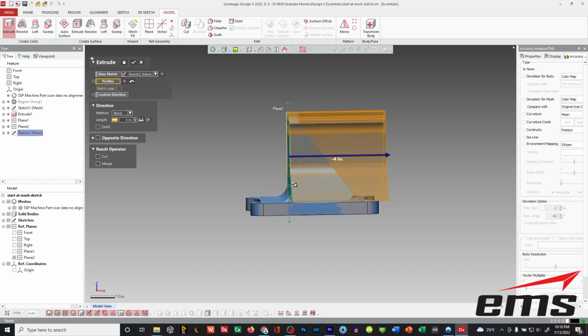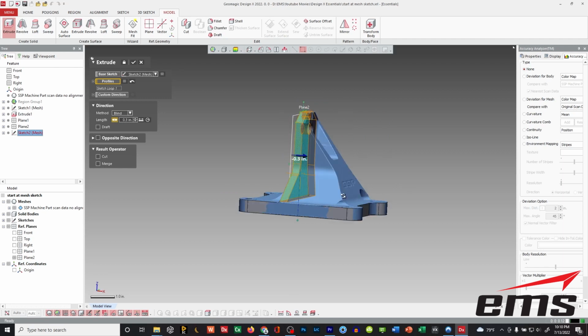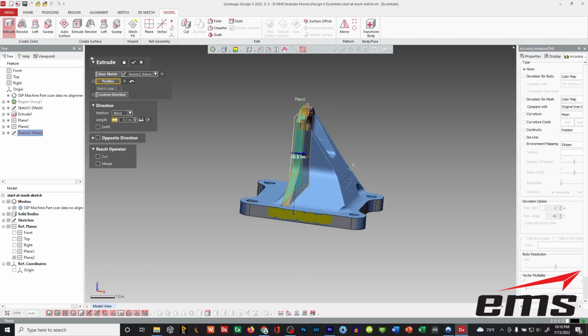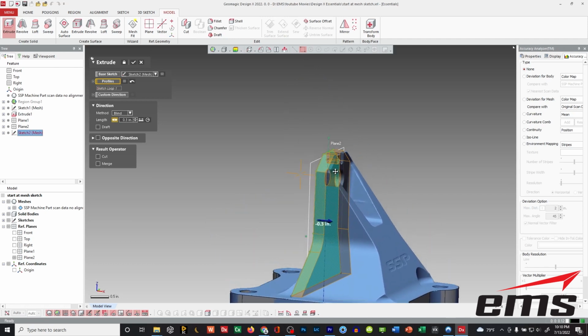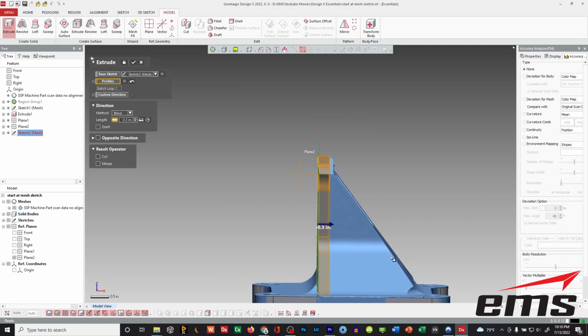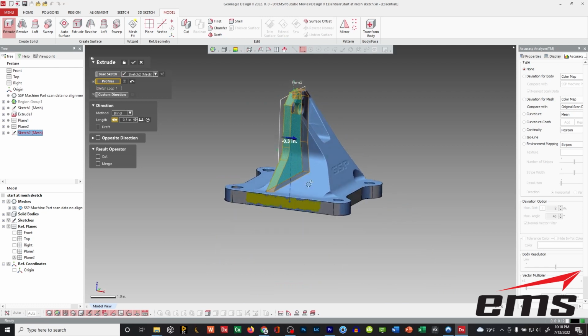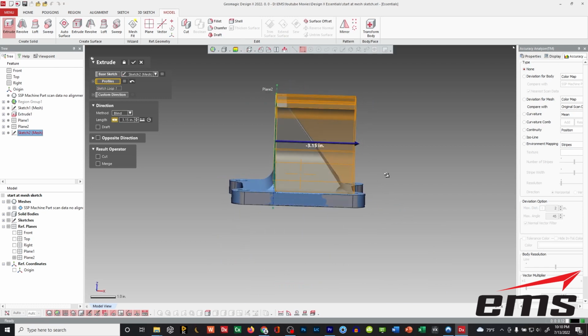Now I'm going to extrude this, and you can see it's on an angle here. Now one of the commands is you can extrude up to a region or a face, and theoretically we could go up and extrude right up to the angle. Problem is it's really two faces, right? You've got this angle here, but then you also have this one here. So we're going to have to do that in a separate operation. So we're just going to pull it out somewhere beyond this face. We're not going to merge them at this point. Let's leave them as two separate bodies.